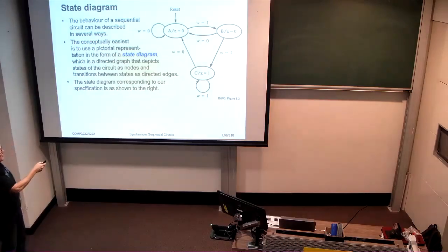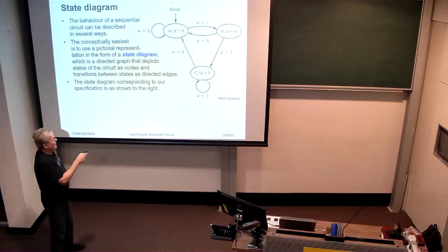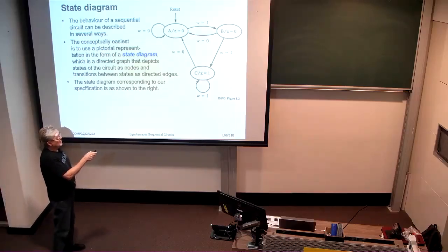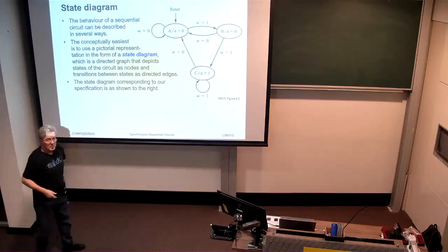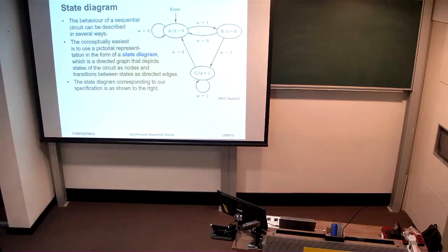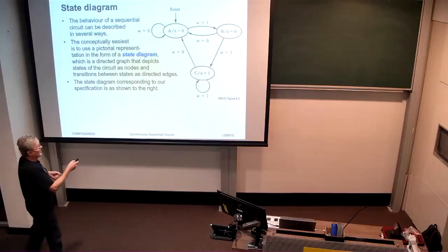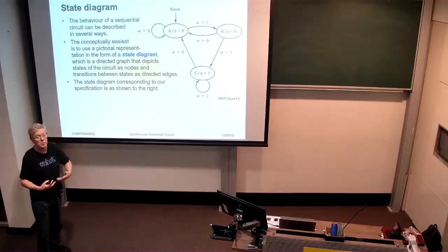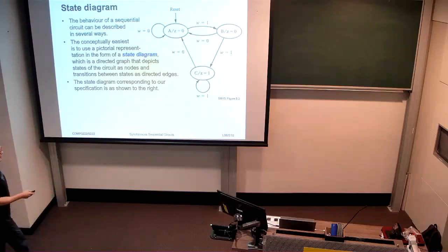And we determined previously that if we get 0 as an input in state A, we stay in state A. On the other hand, if we see a 1 in state A, then we enter state B, which signifies that we've seen a 1 in the previous clock cycle, right? And this transition is meant to happen on the active clock edge, positive clock edge in this particular case. Note that the transition is labelled with the situation that W is 1.